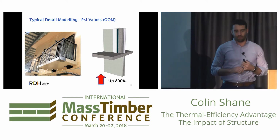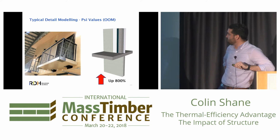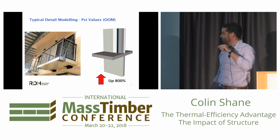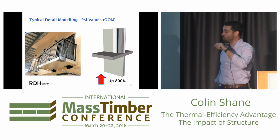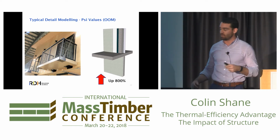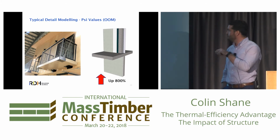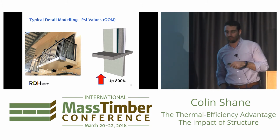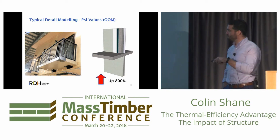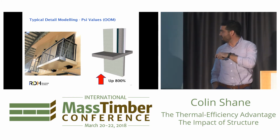Concrete slabs, right? They get a lot of bad press potentially if you start looking at the science of how much the thermal bridging is through concrete slabs that poke through insulated walls. So for interest's sake, if we had an R20 wall here, effective, taking into account thermal bridging through the studs and all those things, continuous insulation on the outside maybe, and we had a wall that was R20, when we slice it through with a concrete slab like that, that R20 goes down to about R10 overall for the building.